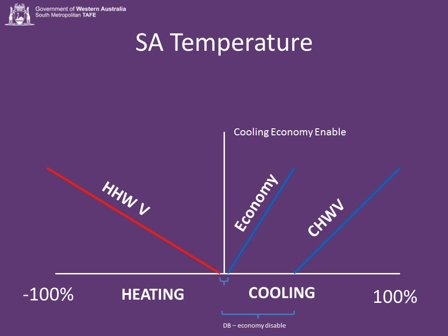And then after say 30-40%, if the cooling from wherever I'm getting it isn't sufficient, then I'm going to use the chill water valve. In the event of the outside air not being available for cooling, what that means is the dead band just gets bigger. Well, I can live with that. It saves money.